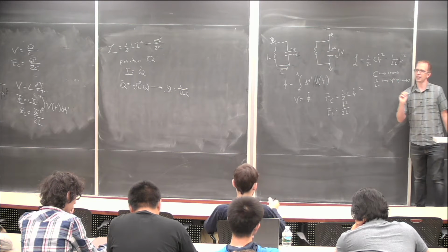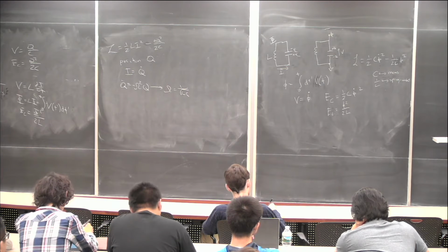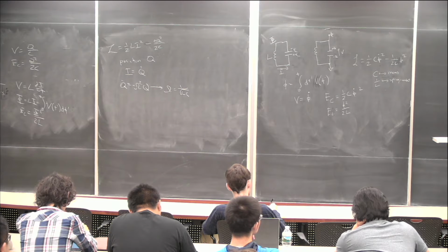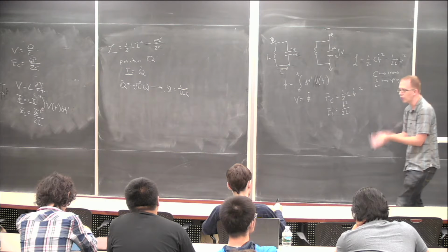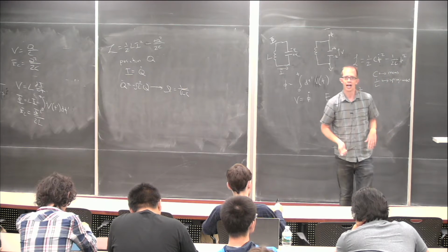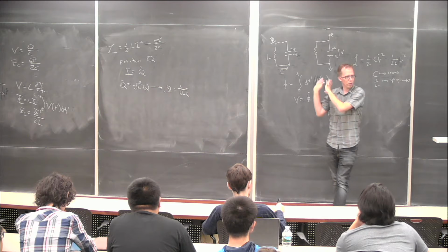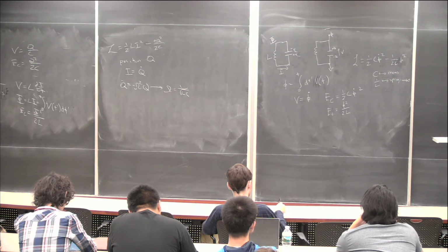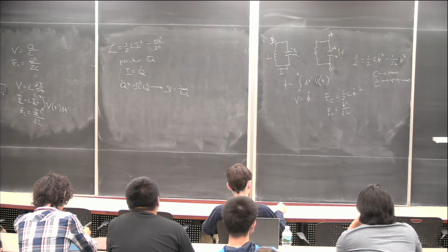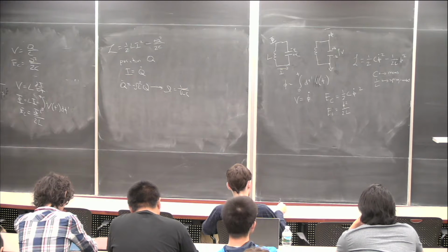This is a useful thing to keep in mind, because as we're trying to get an intuition for how these things work, we'll often say things like, oh, we really want this particle to be more localized. Let's make it heavier. And if you know what's going on in the underpinnings, making it heavier means just turning up a capacitance somewhere, or shunting it with a capacitance somewhere.